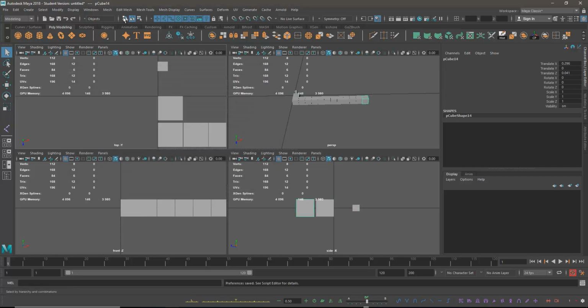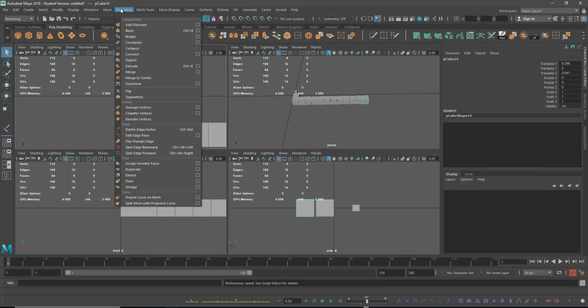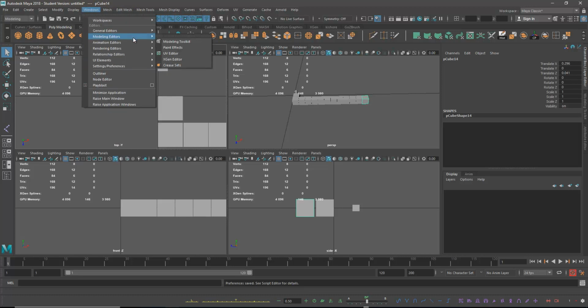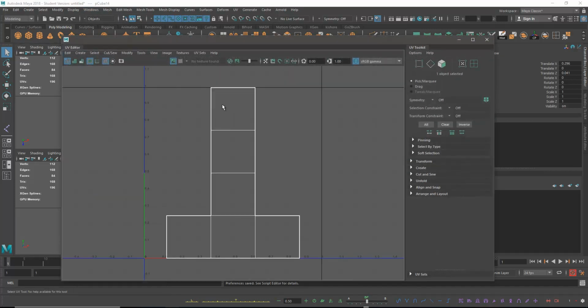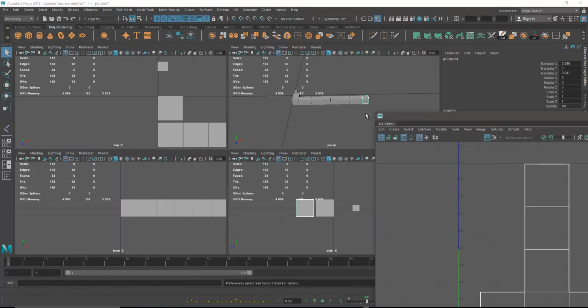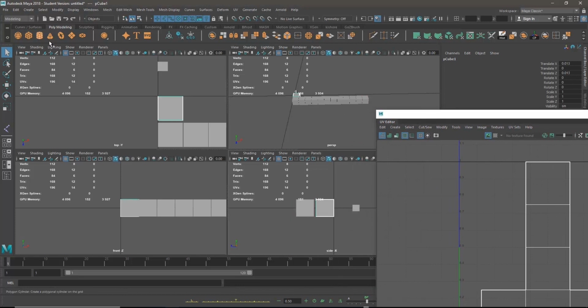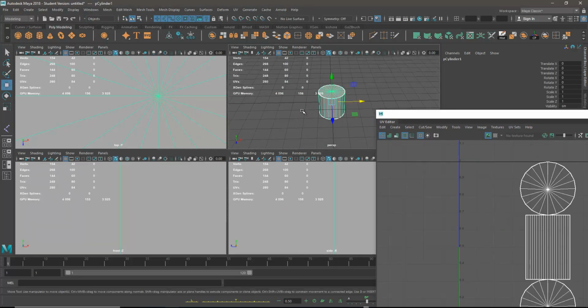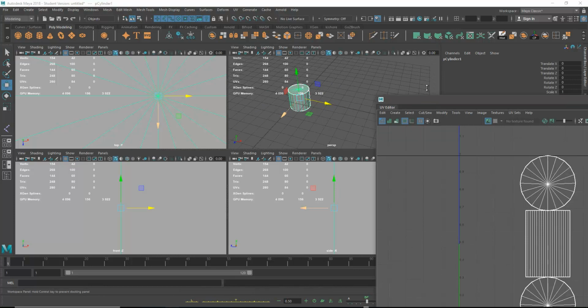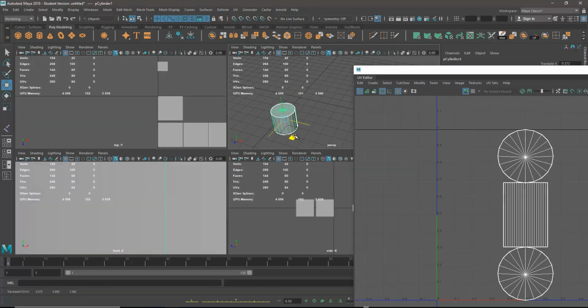So again we'll discuss about all these panels and all. We have a lot of many panels. So for example, see, UV, these are all texturing related. So this is texturing. Generally this is the box, and see, if you select any one box, or if you take cylinder, see how the cylinder, if it is unwrapped, see, cylinder has three sections: top circle, bottom circle, and the middle shell. There are three shells here.